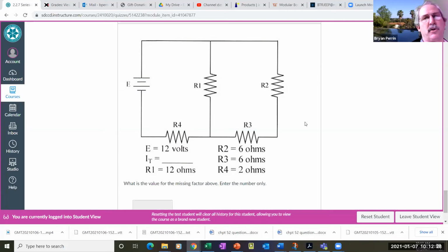They're parallel circuits. Each are a series circuit. So since resistance adds for total resistance in a series circuit, even though R2 and R3 are different resistors, I can treat them as one resistor for the point of the circuit, because the total circuit resistance for this circuit is the same as the resistance for this circuit. They're both 12 ohms. That's why I'm able to do the trick.